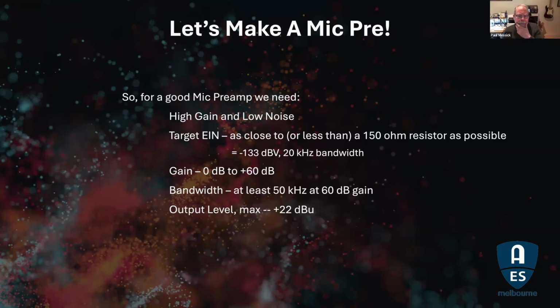Output level, maximum, the normal sort of plus 22 that you can do with 15 volt rails, basically. And at 0 dB gain, line input plus 22 dBu.